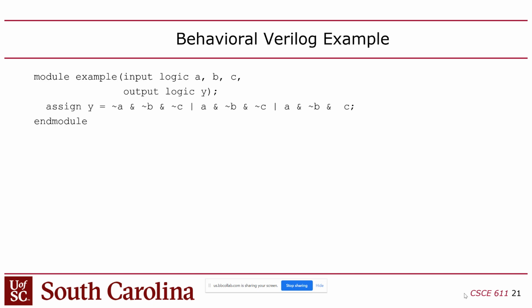And so there's this linkage between the inputs and the outputs. When you simulate this, this becomes a discrete event. This gets simulated in a discrete event simulator, and a discrete event simulator is event-based. So basically, every time they tick the simulator, they have this list of signals which are triggered by certain events. In this case, this line of code will be triggered when any of the things on the right-hand side, which are A, B, and C, change. Anytime any one of those changes, the simulator will trigger that event and update Y as a response.